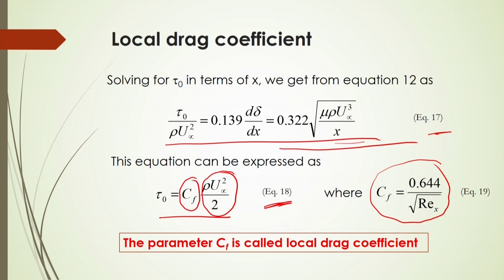So, this parameter Cf, the local drag coefficient, is very important to model the flow over a flat surface under boundary layer conditions. Based on it, flow devices are also designed for a range of highly viscous flows, in that particular physical property condition. You also have to know what the drag coefficient should be, because this frictional drag gives you the loss of flow and energy during the flow, so you need the local drag coefficient to calculate the energy economy of the flow process.